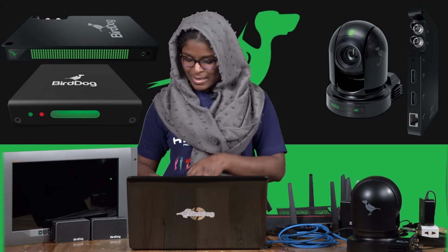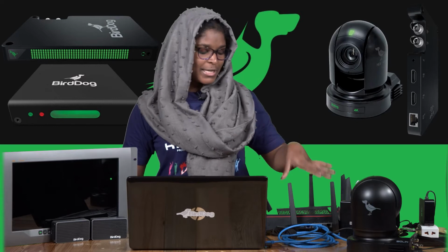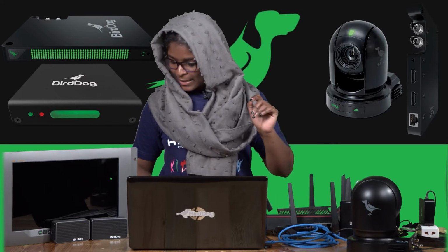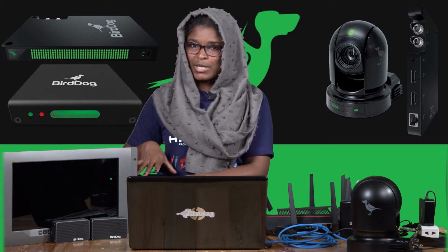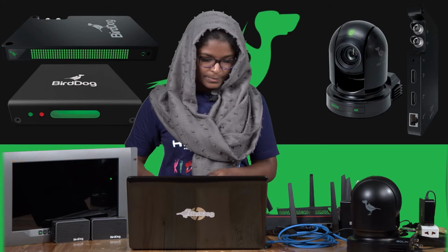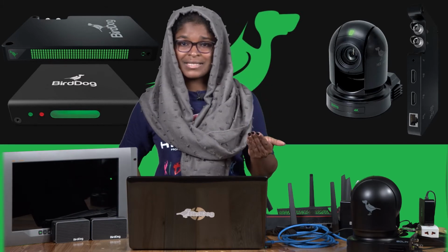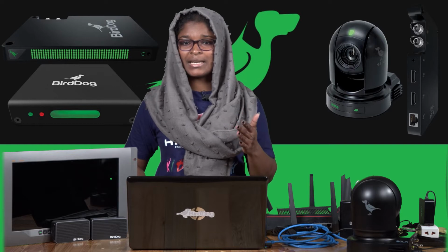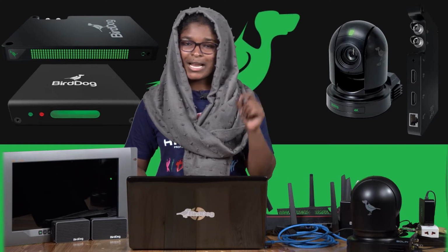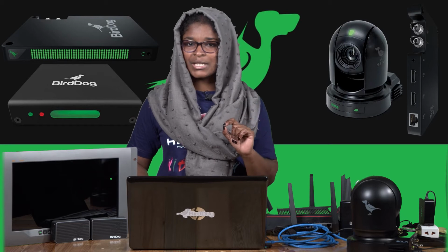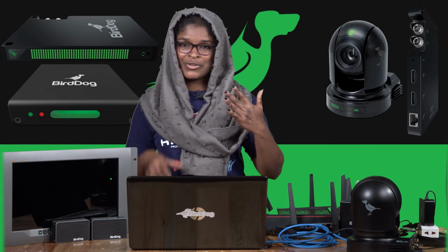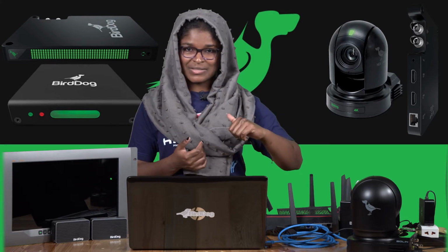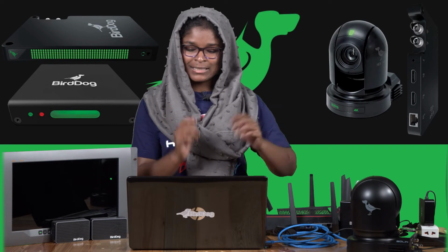Well guys, I have everything already connected. I have my camera, my laptop and the BirDog unit, all of them connected to the Asus router. And then another connection I also have is the SDI out from the decoder to the monitor for us to be able to view our decoded signal. And that's it. On our last video, I had explained about decoding. I had explained how you can change the IP address of your laptop or PC to be on the same network as your BirDog unit, for you to be able to access the web interface. On our today's video, I'm not going to repeat that process, but you can go back and watch our previous video of BirDog encoding.